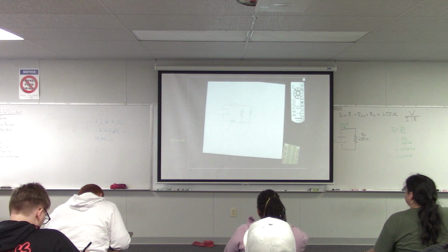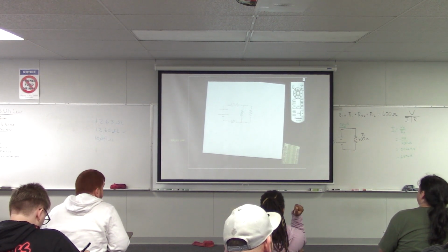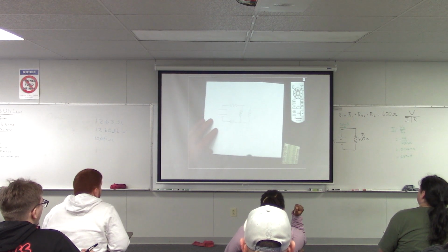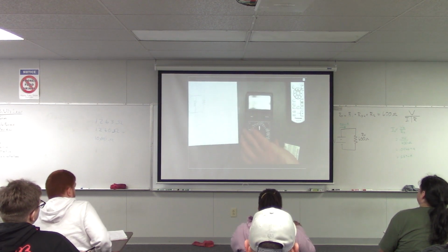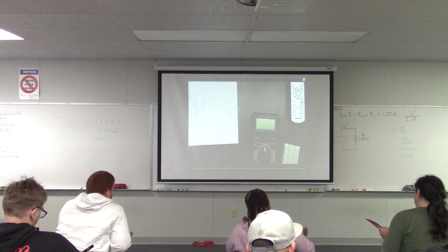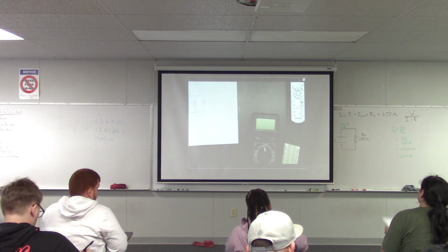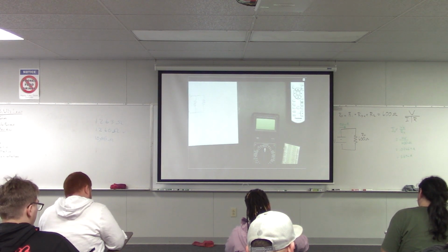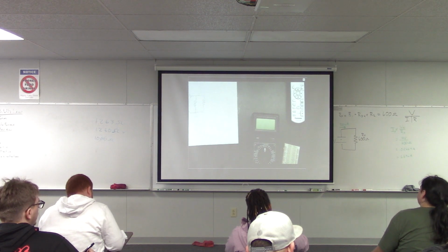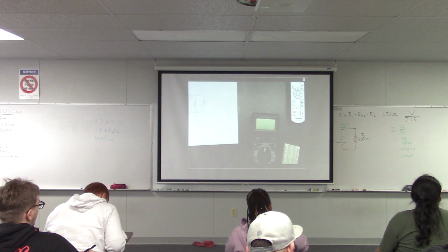The first thing that I recommend is that you go grab your resistors and actually measure each resistor by itself to make sure that the resistor value is what you think it is. Because even if you pull a resistor out of the 1 kilo ohm resistance bin, that doesn't guarantee that it's a 1 kilo ohm resistor. People put resistors back in the wrong bins all the time by accident.